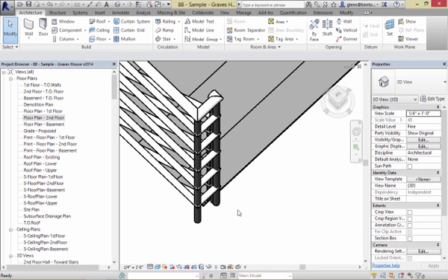For this type of design development work, you're really coming back to the client with the very first model. They're going to tell you, that's nice, but what if the stair was over on this side of the house instead? At which point the 4 hours you spent getting that 1/8 of an inch precision, you'll feel like, oh, I wasted my night. So don't do that. Allow yourself this notion that some things are off just a little bit. For this type of modeling, we don't need the perfection yet. We don't really have to fix it, but it's going to take a little bit of messing around to figure out why that's off by 1/8, and it really has to do with how the rail's defined and the parameters, and there's something about the offset relative to the line, and we'll figure it out. But don't waste your time right away.